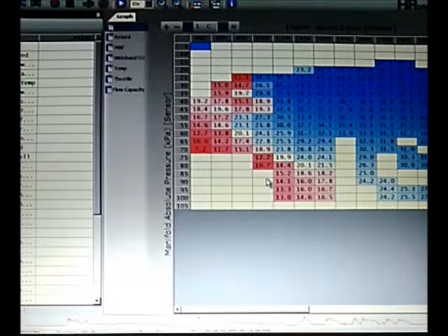You have to make very small changes. Sometimes even if you need a 5% change to a cell value, you don't want to actually make that 5% change all at once. You want to make it in steps, sometimes 1% at a time, so you can creep up on the actual perfect number, because overshooting will just mean more tuning for you, and you could diverge completely and make the number worse. So better to start small and work your way up and sneak up on it.